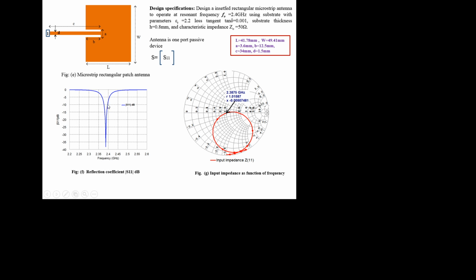See here, within minus 10 dB, from here to here, F1 to F2, we can get maximum radiation. For maximum radiation, the reflection must be at least less than minus 10 dB. From this frequency to this frequency, the reflection is lesser than minus 10 dB. So only in this F1 to F2 range does it radiate maximum. So we have to plot this graph.